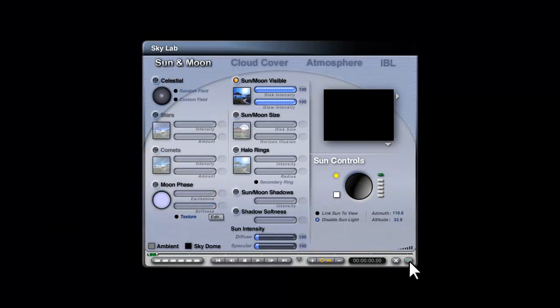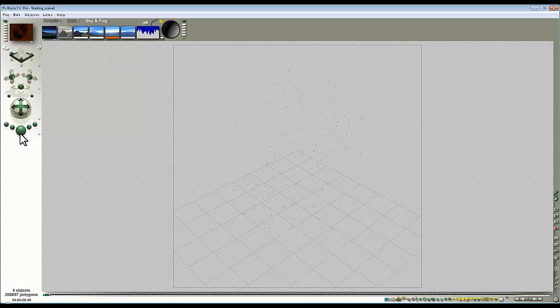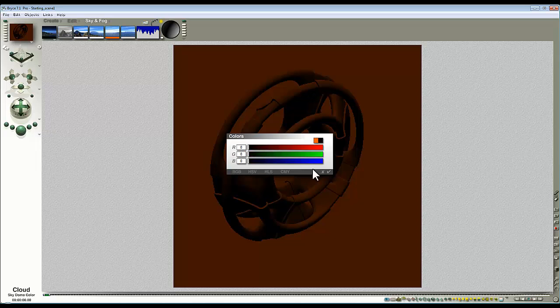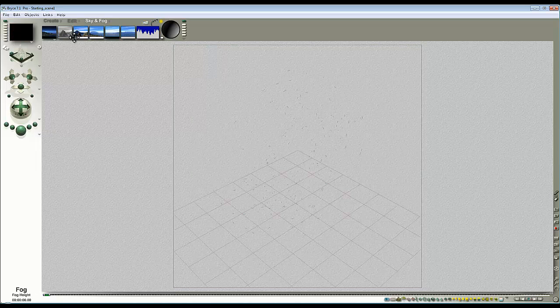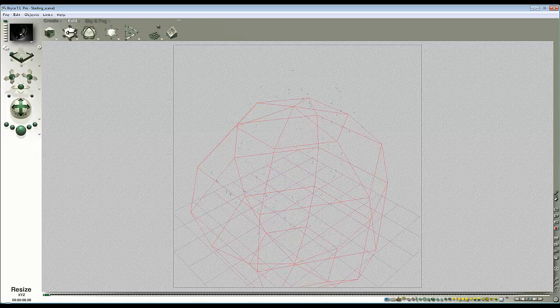So at this point what I should have is a fully black scene, and if I don't, then I have to be suspicious that I got atmospheric effects, but I've got the atmosphere off, so that's not going to happen, or sky dome colour, which is something that can pollute your scenes. So I'm just going to make sure that that's set to fully zero, not even any slight values in there. And as I say, the global ambient colour here is what I'm going to use to drive my effects. I'm going to turn that up to its maximum setting, and at this point I'm going to introduce a light source. So create a light source here and enlarge it, but not massively.